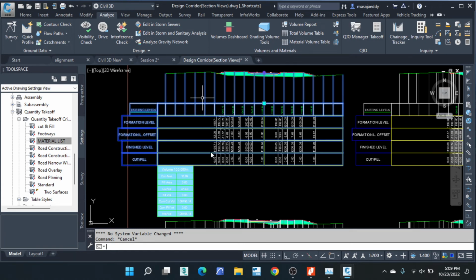Then if you want to place them in a new independent drawing, you select all layouts in one new drawing, or if you want them in the current drawing, you select add layouts in the current drawing. So let's add them in this drawing. So you go to next. We shall use the default name for the sheet sets. Then you shall go to next.